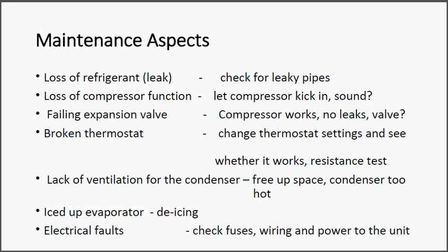A broken thermostat. So you've got a thermostat inside a fridge, and if that one breaks, it might either cool down to crazy levels or it might not cool down at all. So again, the first one is just change. Most of them are very simple thermostats. It might be just a bimetallic strip making a contact. I would mess about with the settings to start off with to see when it kicks in, and then check this with the temperature. Maybe check the connections of the thermostat, the wiring, that it's okay, that it's not corroded or dropped off or some damage to it.